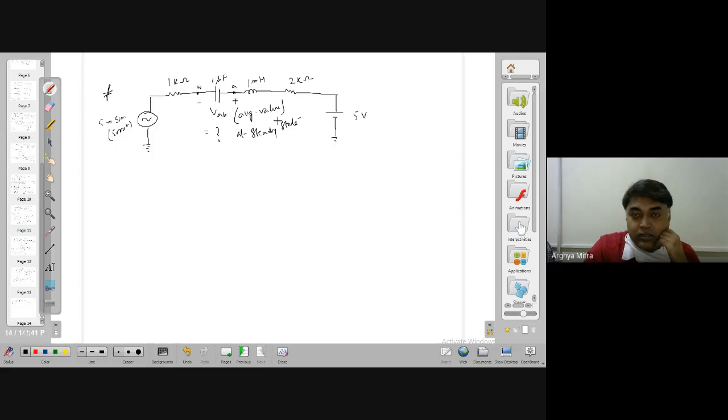So this particular network will not encourage you to solve it. But you see that you know the basics of understanding a network. When more than one energy source is present, go with the superposition. So you have two voltage sources present. Maybe one is AC, another one is DC. Doesn't matter. Superposition is applicable to all linear networks. All linear elements are present, so I can apply superposition.